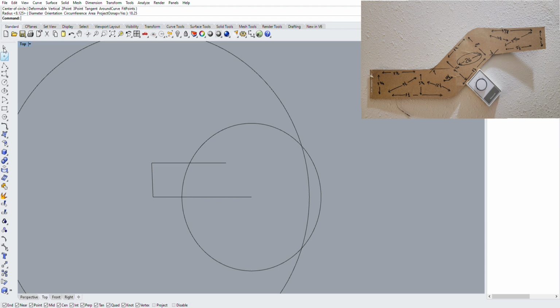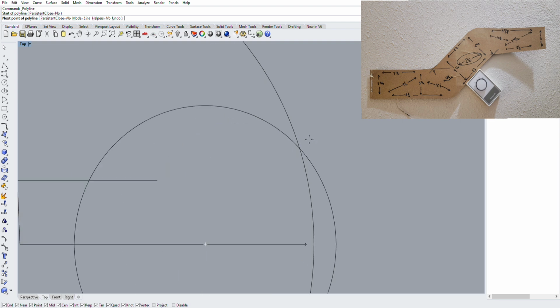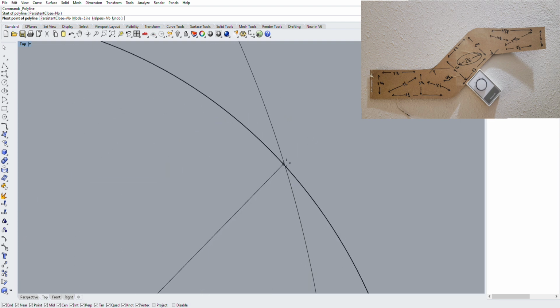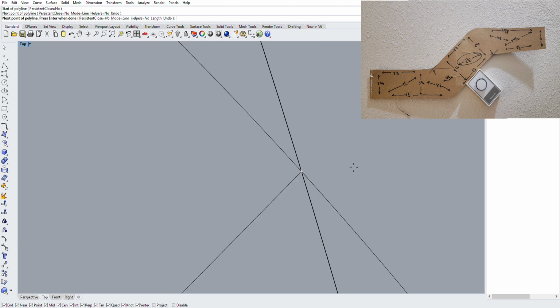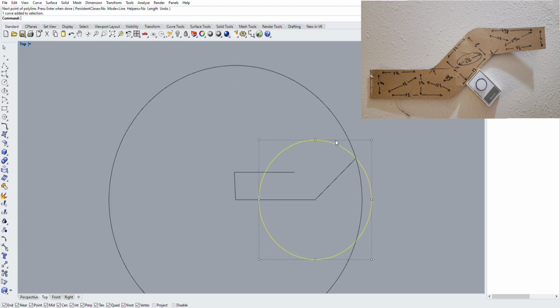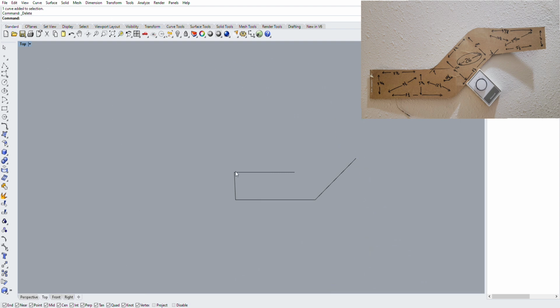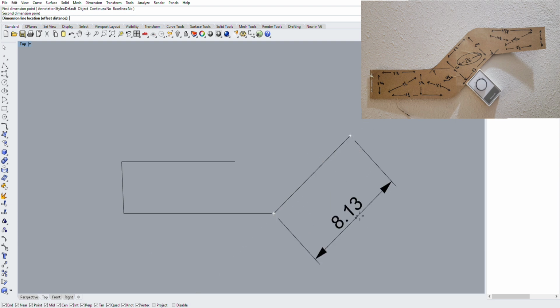point. Now, literally, over and over again, all I'm doing here is I'm going back to my drawing. I'm starting from one point to another point, and I'm using my circle command on radius. And that's going, if we're starting from a known point, and we have two dimensions giving us two radiuses we can use, we already know that it can only land in one spot in space. That's why you see it cross. Well, it can land in two. The circles will cross over in two spots.